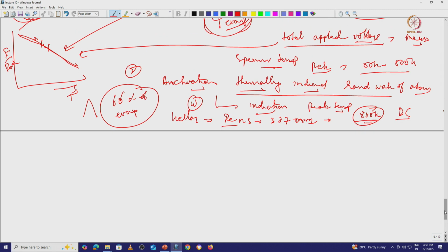Now we have talked about the peak temperature, and also we can estimate the cooling time. This cooling time of the tip surface depends on the ability of the tip surface to transfer the heat acquired at the surface towards the core or along the tip axis.